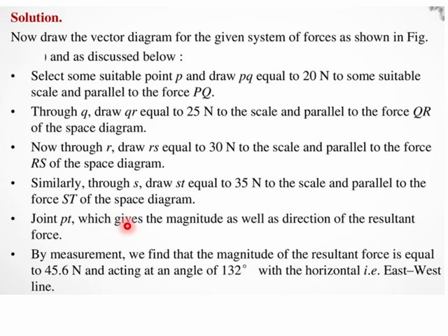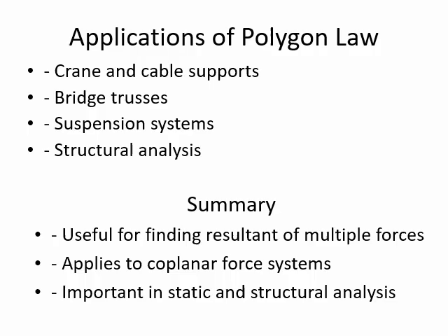The closing side of the polygon becomes the resultant force. So this closing side can be measured, and based on the suitable scale we have selected, we can calculate the magnitude of the resultant force, and the direction will be calculated based on the angle from the diagram.